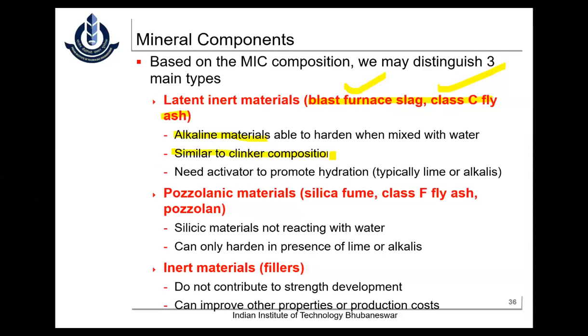Like if you take blast furnace slag and mix it with water, definitely after some time it hardens. I mean, it has some hydration phenomena because of the lime in it. The only thing is it requires a small amount of some activator to promote the hydration. You can use a small amount of cement, lime or an alkali.